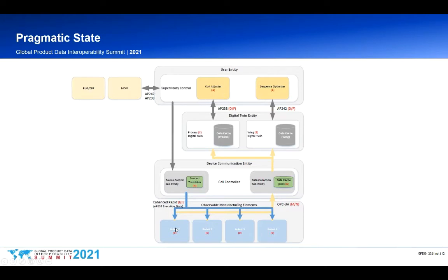And so what has come up is taking third-party optimizers and developing this concept of enhanced G code, where we work inside of the constructs and the organization of G code itself, but we get creative with it to be able to bake in the sequencing and new information we have from the CAD information, as well as the manufacturing information.